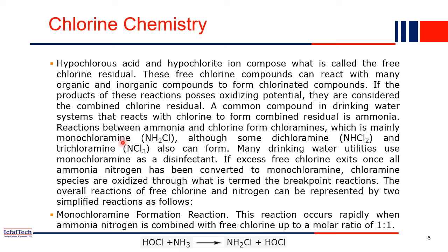This monochloramine is the compound which is very useful for disinfection purposes. Many drinking water utilities use monochloramine. It will enter into the virus and bacteria cell and destroy the virus and bacteria. Excess free chlorine appears once all the ammonium nitrogen has been converted into monochloramine.